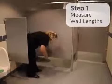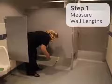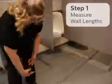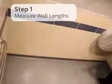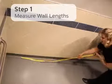So, step 1, measure the wall length. When measuring the wall length, measure from the wall to the outermost edge of the partition panel. Since the ADA stall is an alcove, I need to measure the adjacent wall as well.